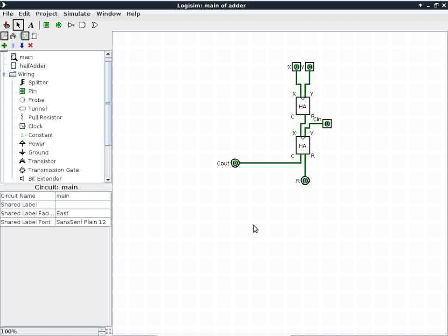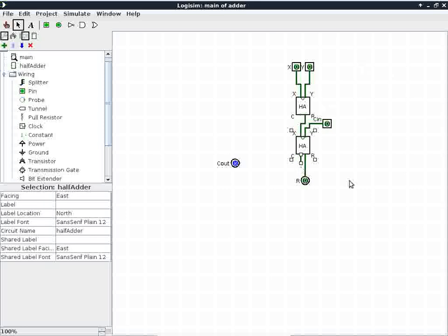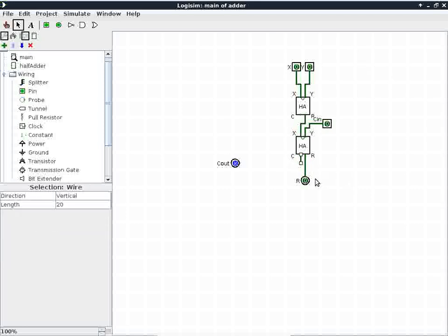Well, no, I take it back. Okay. So let me just do this part here. Okay. I have one single carry out, but I have two output carries from the two half adders. How do I combine the two output carries from the half adders to the output of the full adder? Do an OR, exactly.